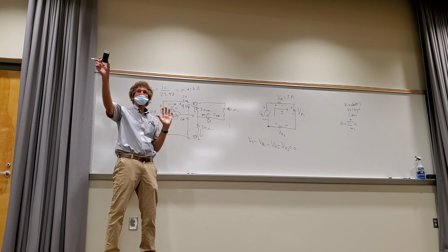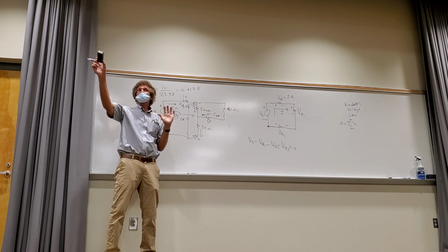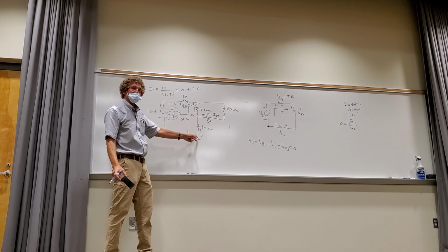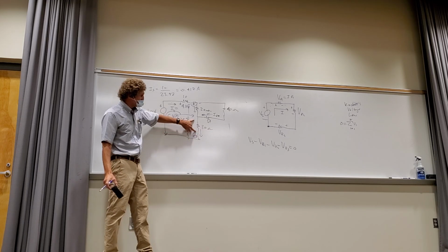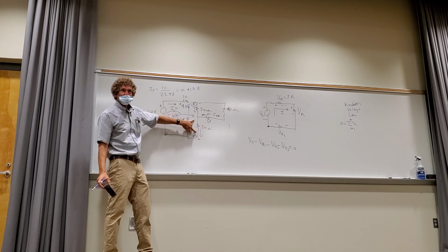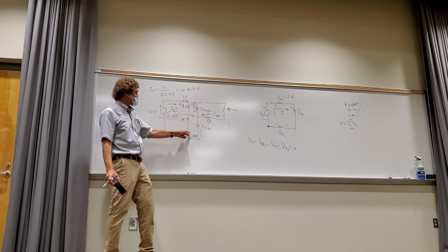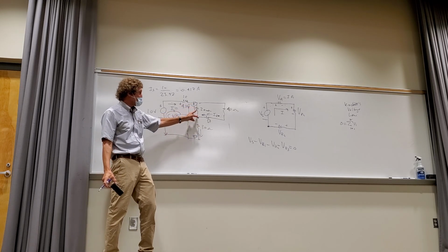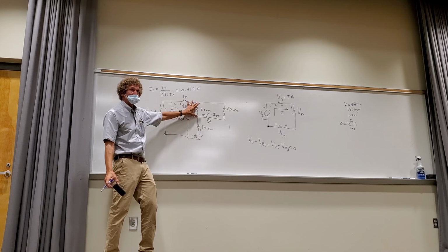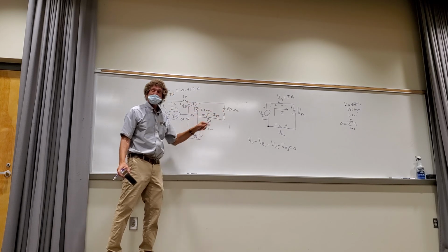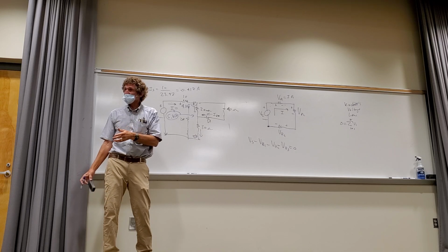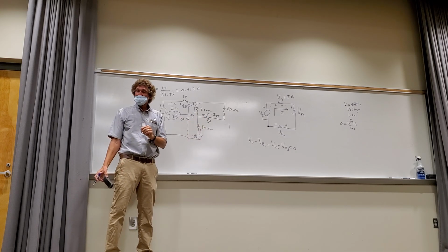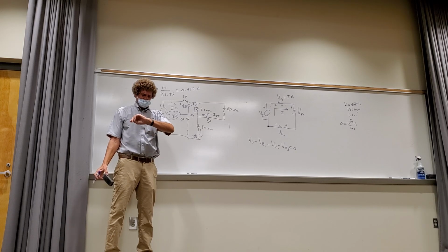No hands right there in the middle section. Do you understand what I was trying to do? What I'm really trying to do is figure out the current through here. Once I have that, I have the voltage drop there. Once I have that voltage drop, I can subtract it from, as you said, the 5.83 to see the voltage remaining. And I know since that voltage is across the 20, it's also across the 90. I divide by the 90 to find the current, because I wanted the current through there. That's one way of doing it. I don't want to burn you with that one.